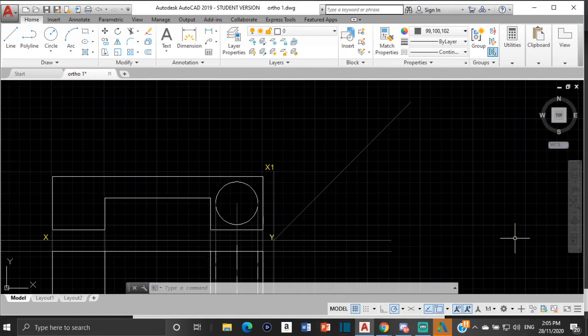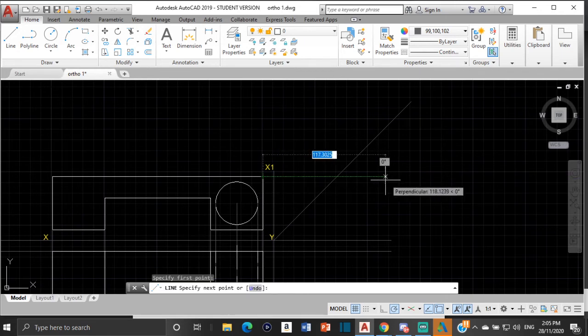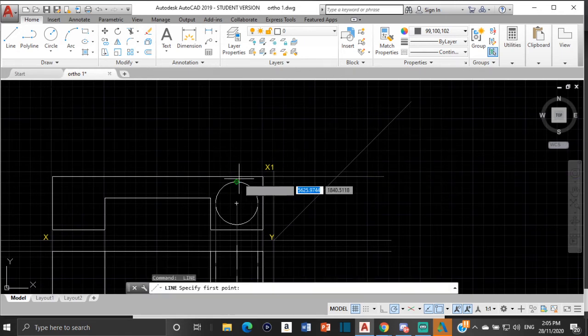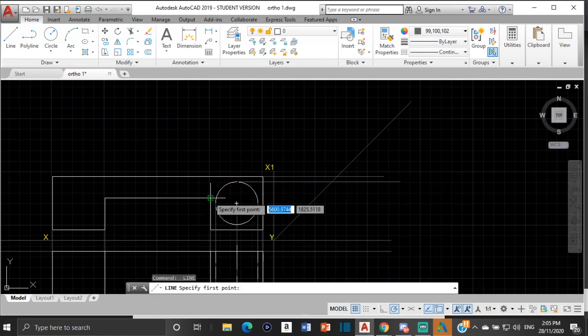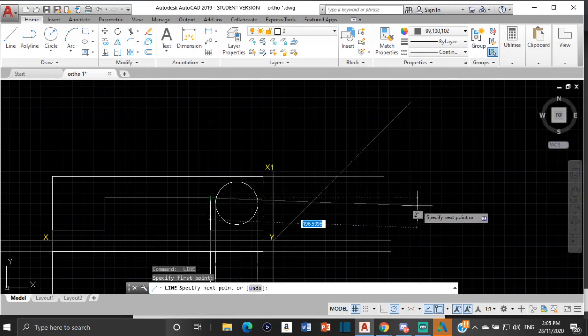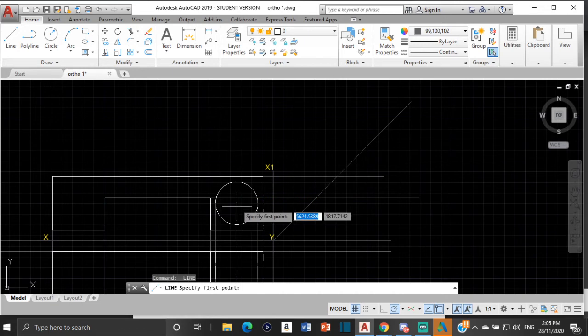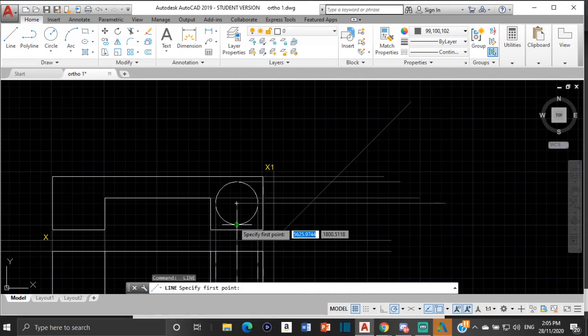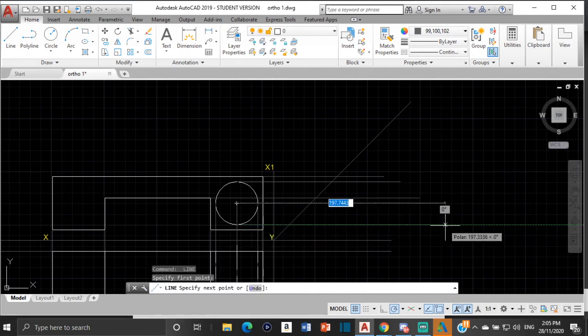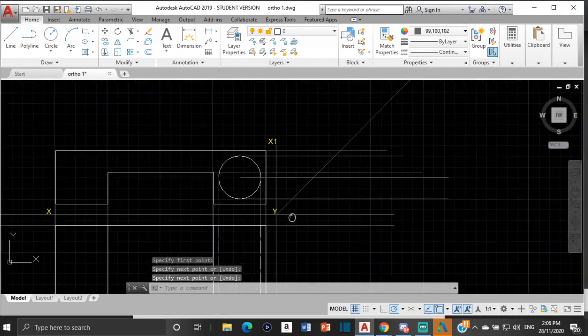Now, from all these edges here, from the plan view, we're going to draw lines across to meet that 45-degree line. Then we're going to move those lines down. I'm going to draw lines across like that. Also from here, that's the edge of the circle. From this edge here, from the center of the circle, from the edge of the circle. We're not bringing across the lines by any specific measurements right now. And then the edge of the figure itself.